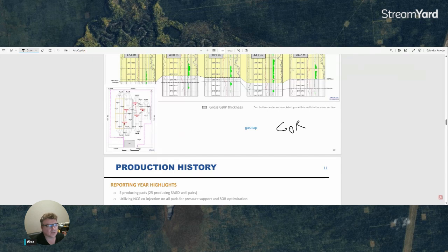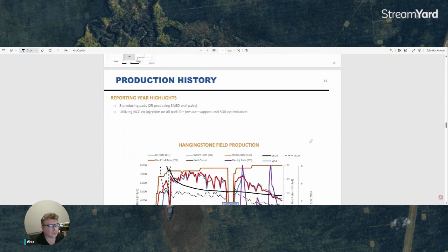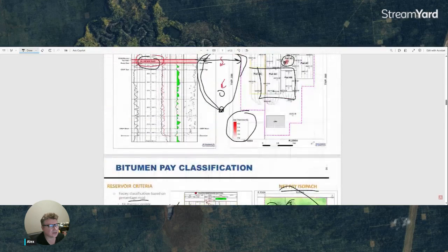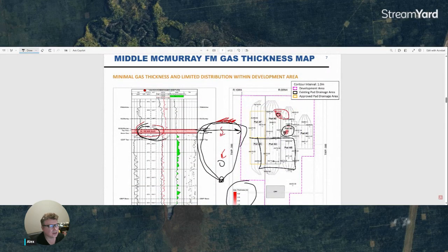But I think one at this point can identify why it's important. If you're looking at the gas zones that we talked about here, and let's say you're operating that pad AD, you will pay extra attention to the GOR metric, gas to oil ratio produced. Because if you're producing from the top zone, you now know that maybe you compromised the operational chamber conditions, and you have to closely monitor the chamber development.